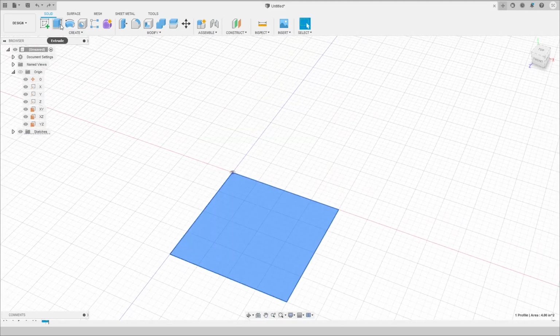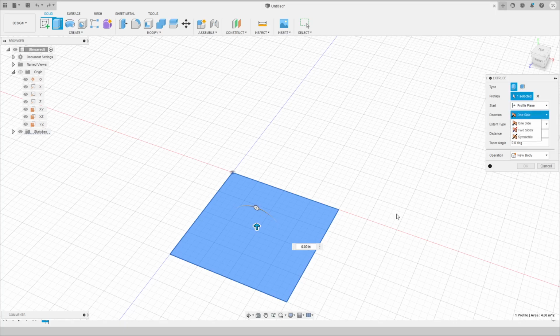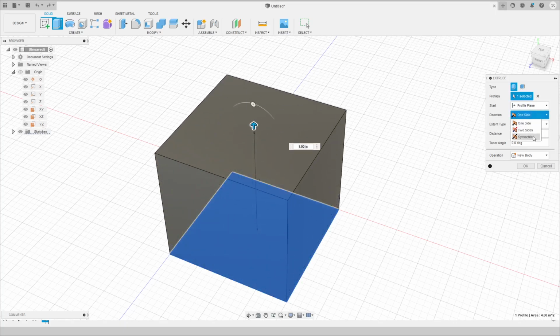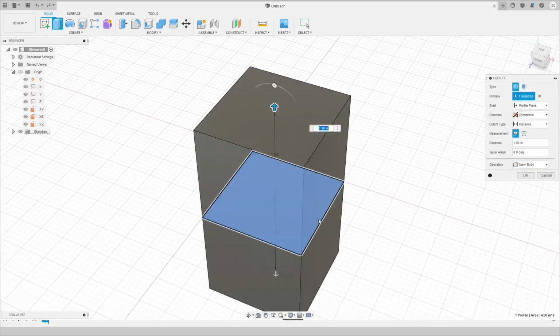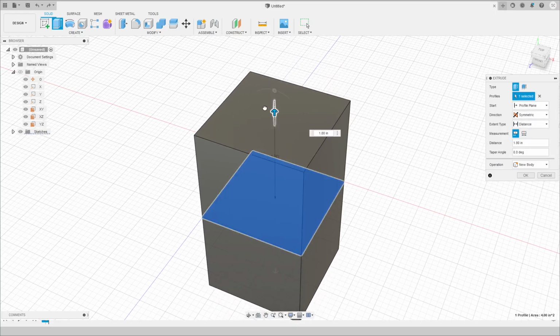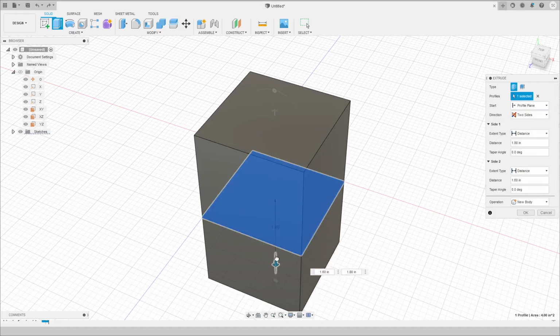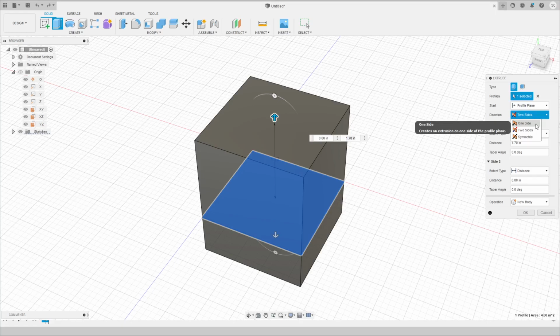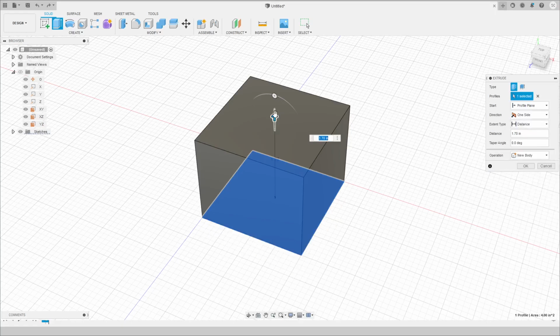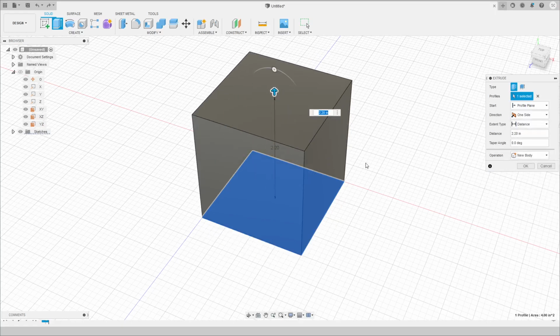There were a few important attributes to how we did that. The basics of how extrusion works: we're using one-side extrusion, as opposed to symmetric extrusion. Let's zoom out a little bit. You can see the plane we're working in, and some stuff below and some stuff above. That's because with symmetric, instead of extruding on one side, the symmetry mode makes it extrude on both sides of the plane from this object. With two sides, we get to determine how far it is on both sides. It's not always going to be exactly the same.